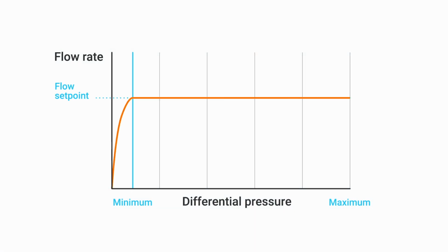Repeatability and accuracy is a big question around this type of valve. If you look closely at manufacturers' data sheets, they'll often state a flow tolerance of plus or minus 10%.